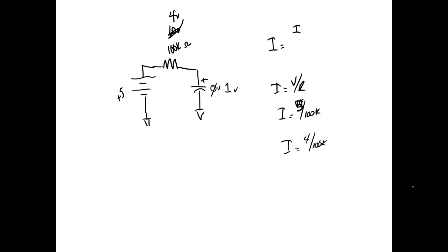It went down, right? Okay. When this charges up to 2 volts, that means I've got 3 volts up here. So what happens to my current flow? It goes down. This guy charges up to 4 volts, this guy goes to 1 volt. What's happened to my current flow? Okay. This charges up to 5 volts, this goes to 0 volts. What's my current flow? None.